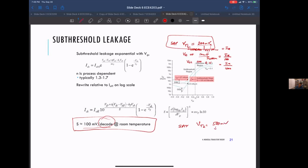Notice that again, the same value holds. At every 100 millivolts below, my leakage current goes down by a factor of 10. So by the time I get to VGS of 0, I get I sub X over 10 times 10 times 10 times 10 times 10. The lowest I could get in the first device was I sub X over 10 times 10 times 10, or I sub X over 1,000. Here, I can get to an I sub X of, what the hell is that, 100,000?